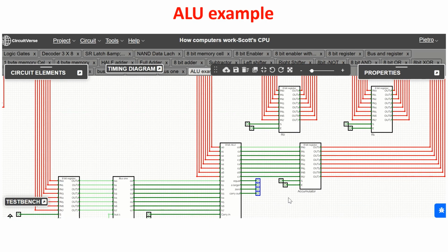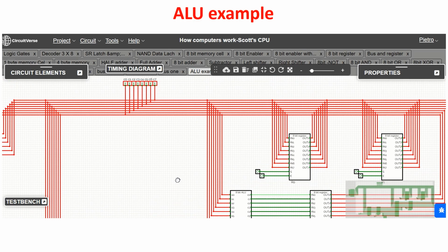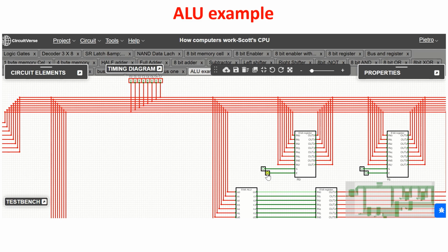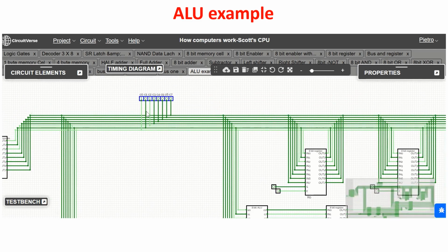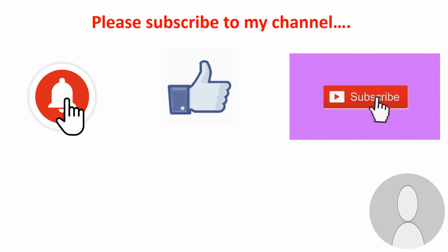And now we store this result inside R0. So we put the byte on the bus from the accumulator, and we store it in R0 with the set input. Now we free the bus, and let's see what there is inside R0 now, and there is the number 5.